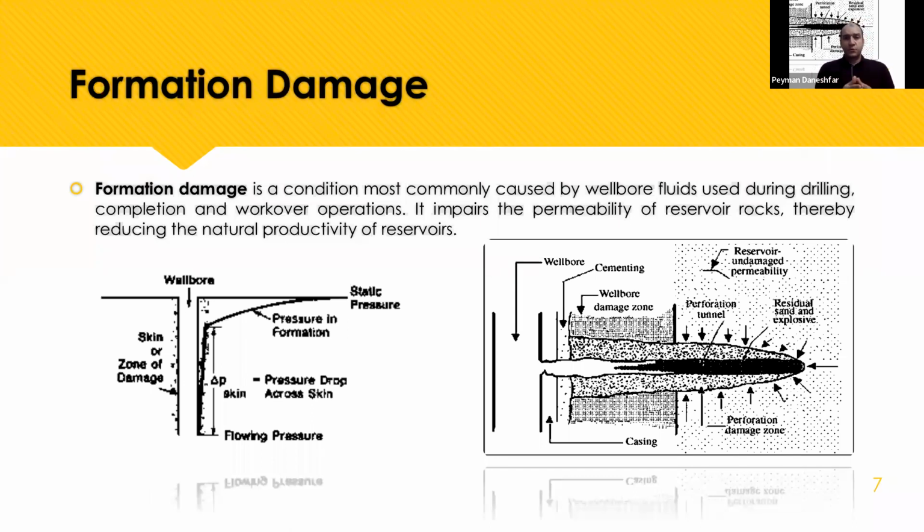The formation damage can be large or small, and each formation damage needs the best cure for it. It means that when you encounter scale, you should use a scale inhibitor, not acidizing.